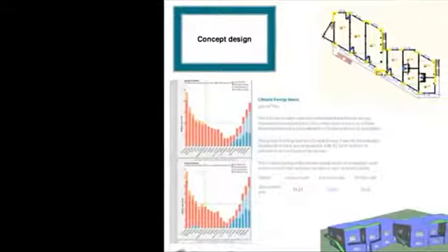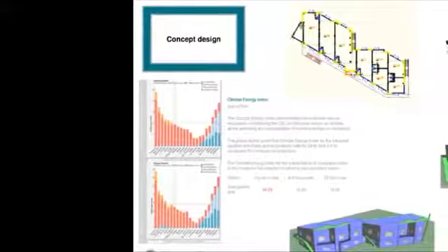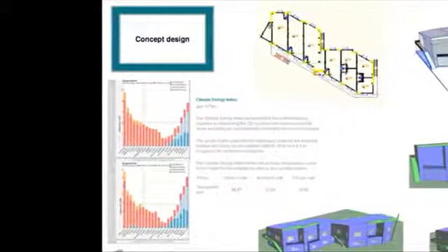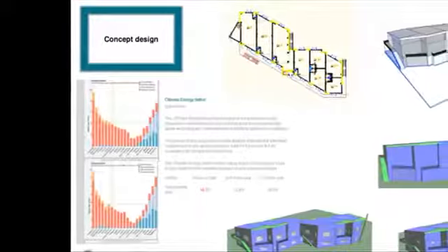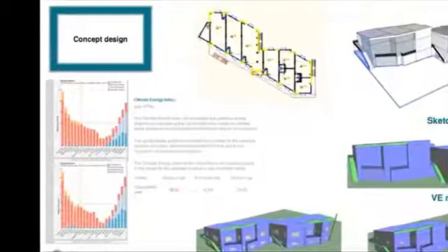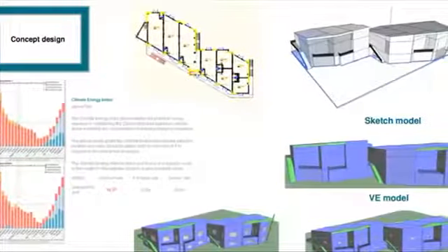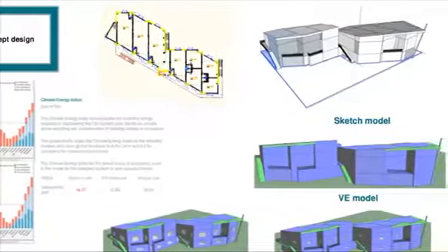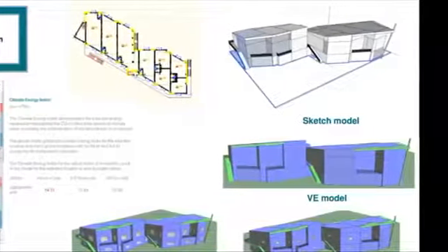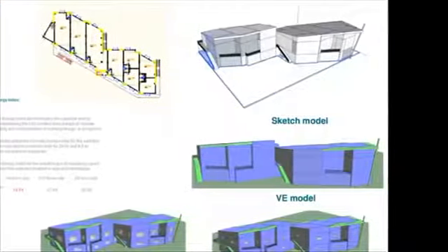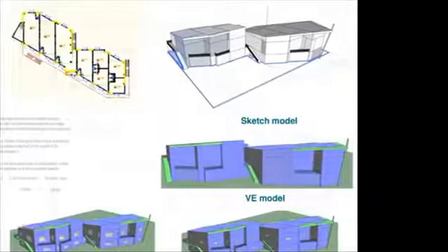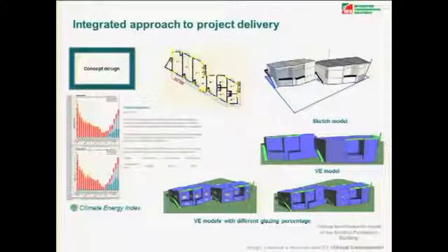Okay, concept design, we may be looking at multiple options in concept design. We'd be getting some comparative studies out of that. So, you know, does a tall model with a fairly compact footprint building perform better than a low-rise version, same gross floor area, which is more dispersed in its footprint? We can start to refine things like orientation, solar shading, glazing percentage, but still at a fairly high level. So making decisions as we get feedback from the model, okay, from the analysis.